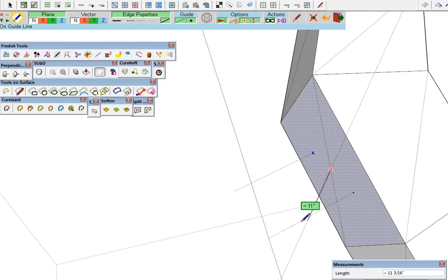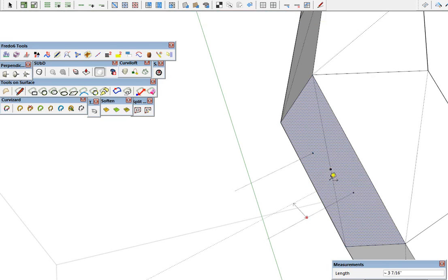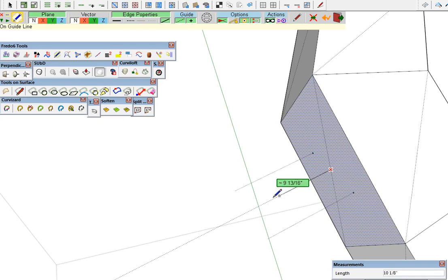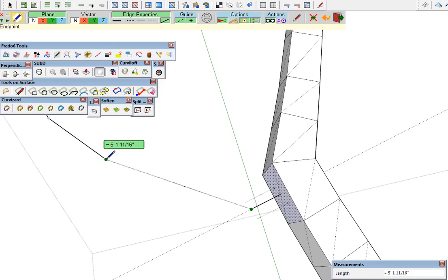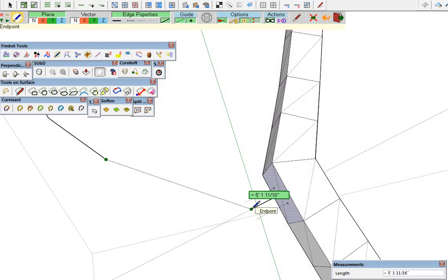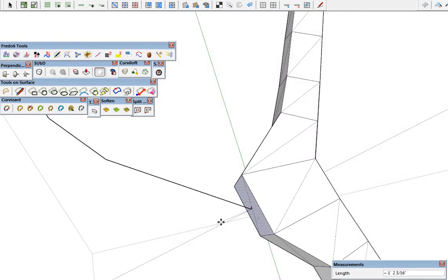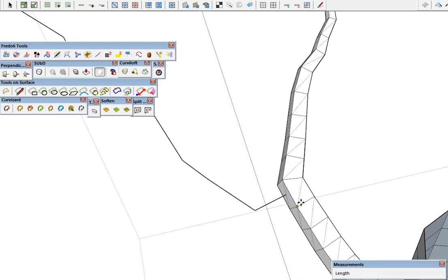And sometimes if you just hover over those, you can come out or just grab those and pull a line out into the middle. And now we can start out, make sure we're perpendicular, and then come up and snap there. And I'm just going to deselect that and move that endpoint over just a little bit and delete those guides.